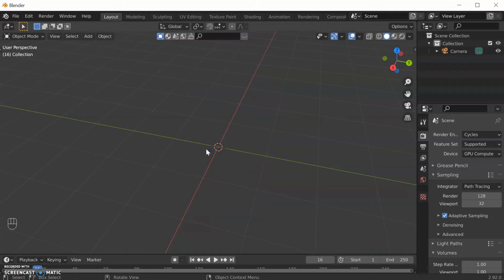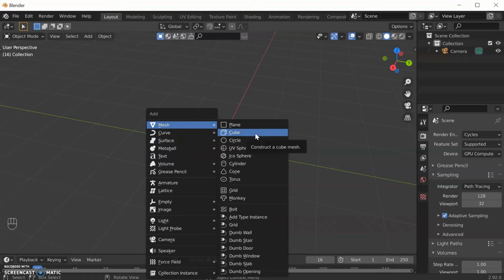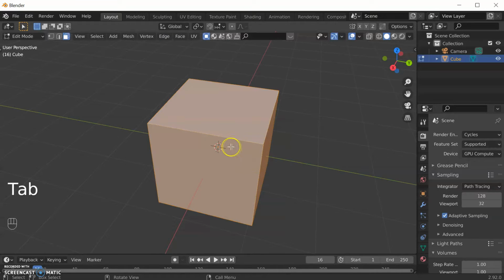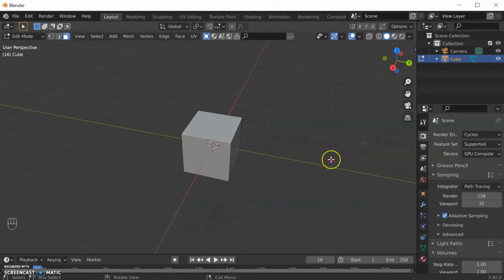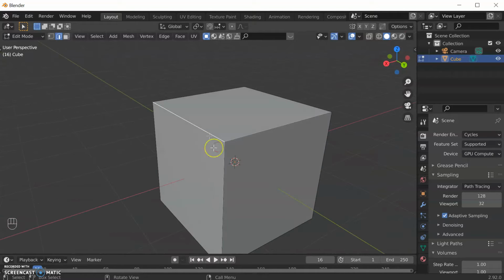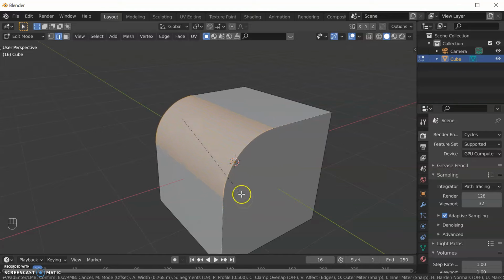Another thing you can do is called beveling. So let's create a cube, Shift A, create a cube. We don't always want a nice hard edge to something. Sometimes the computer freezes up. There we go. Sometimes we want a nice soft edge. So for this we want to select an edge like this. And if I press Control and B at the same time, it will bevel it, it will smooth it out. But more than just smoothing it out to one level, if I scroll my mouse wheel up, I can get loads of bevels in and create a nice shape.